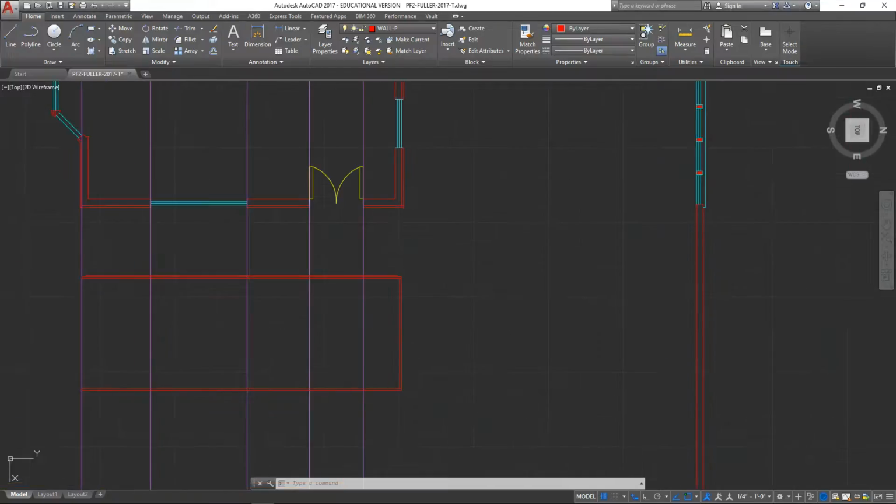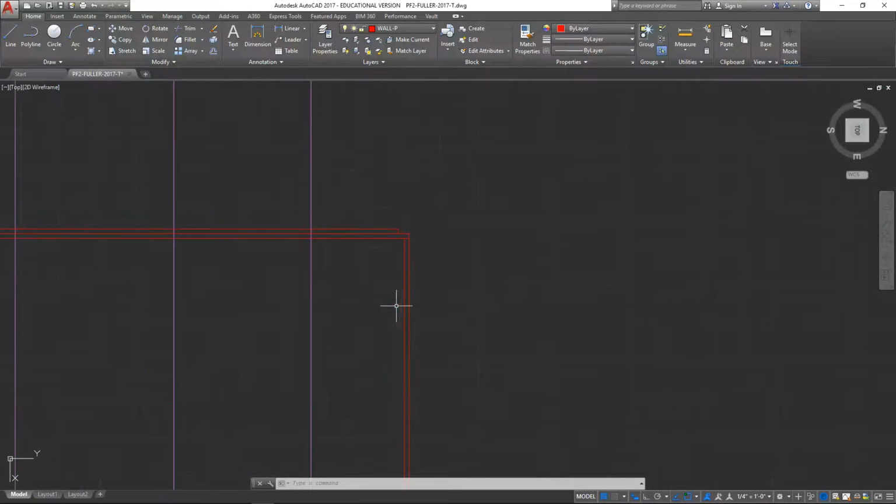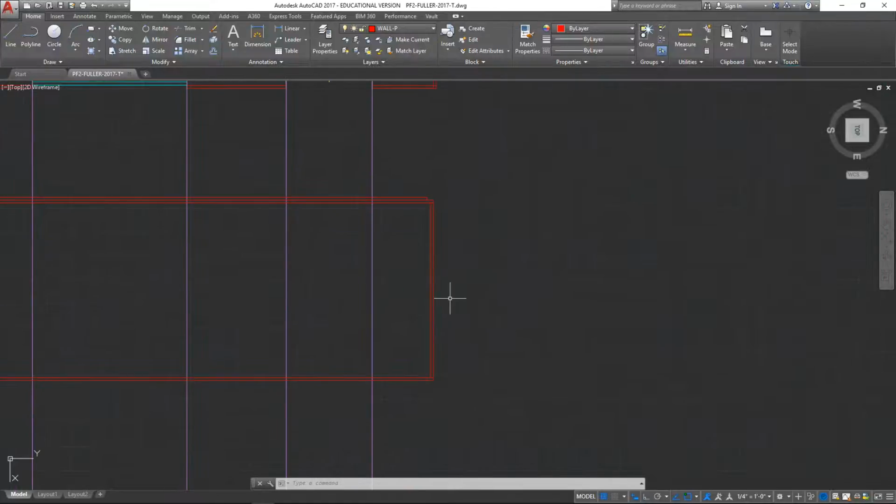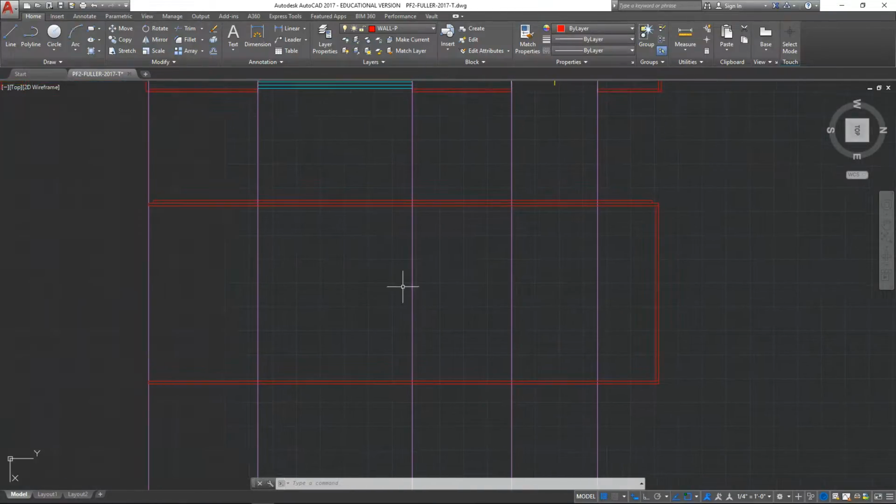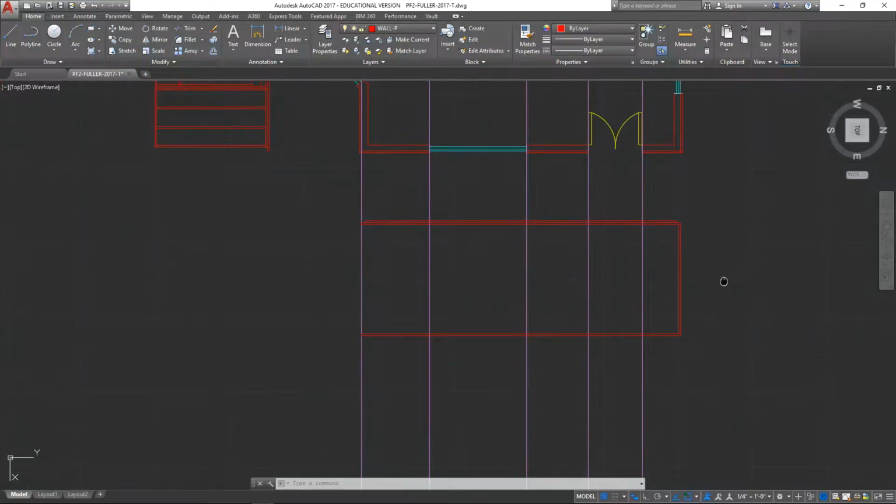We left off, I had created both my top plates on my wall here and then my bottom plate. And this is the far right stud that kind of caps the end. What I want to do is duplicate that stud and distribute those duplications all the way across on 16-inch centers. And here's the way I do that.